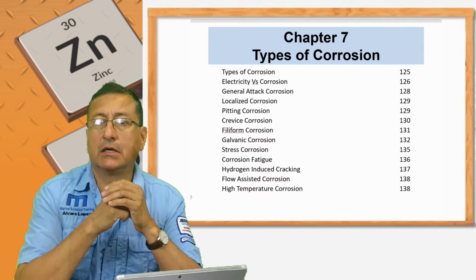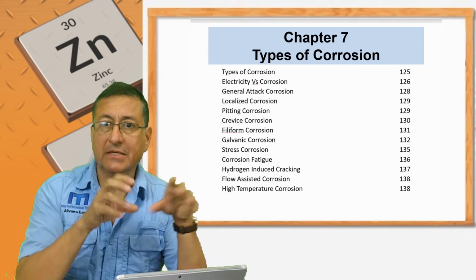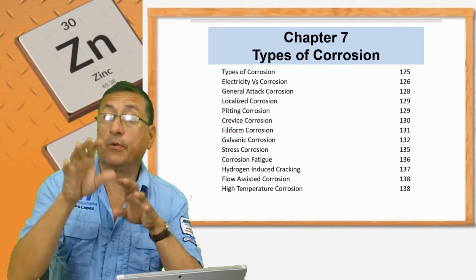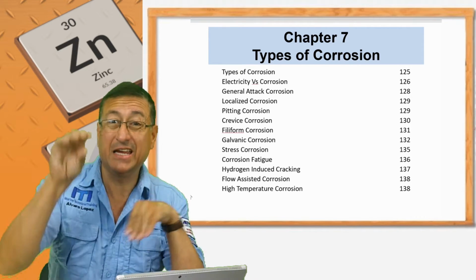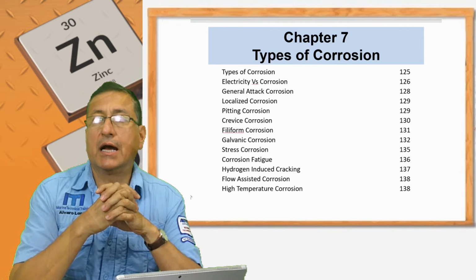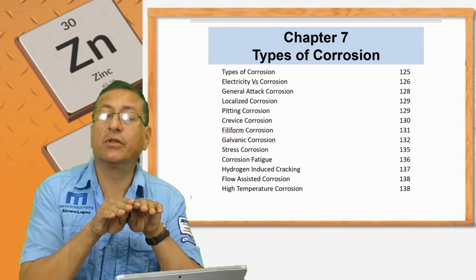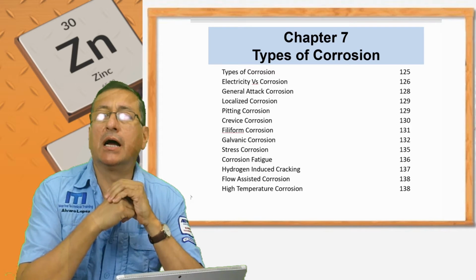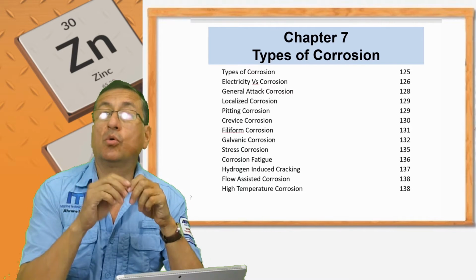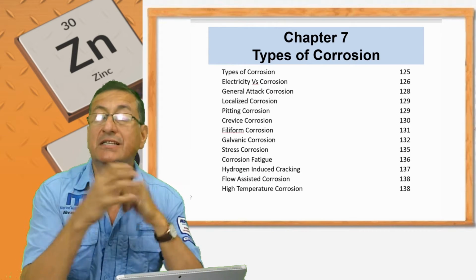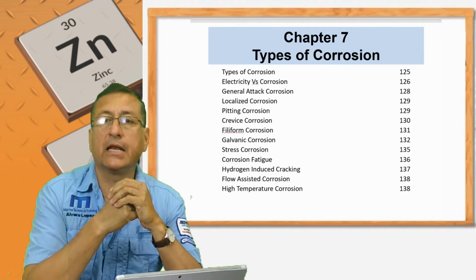The materials: are the elements selected appropriate according to their location in the periodic table, according to the difference in electronegativities? And additionally, if there is humidity in between both of them, that's not good. And additionally, if you have leaks of current, or a current passing through those similar metals, those factors affect the corrosion highly.